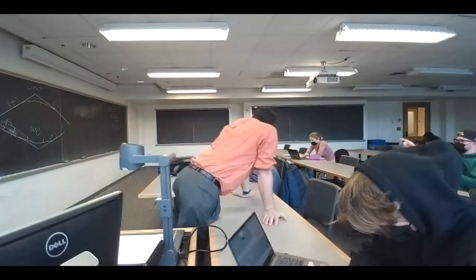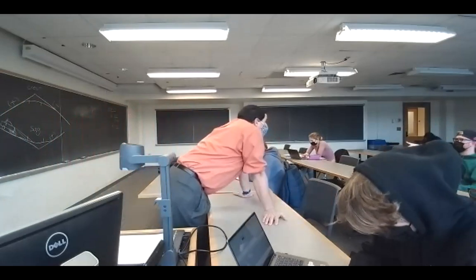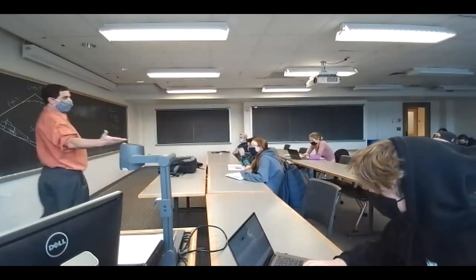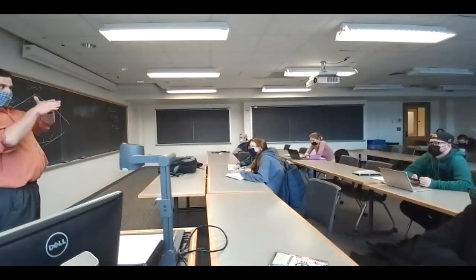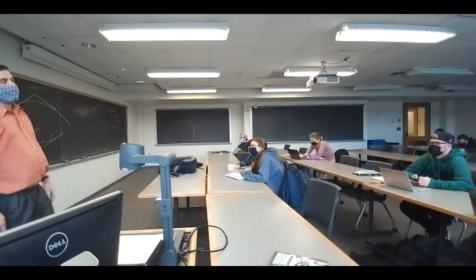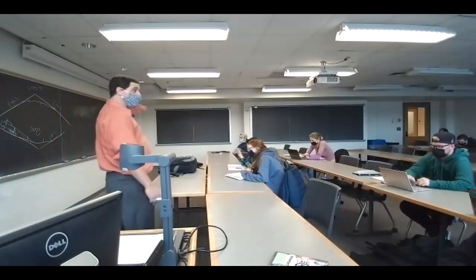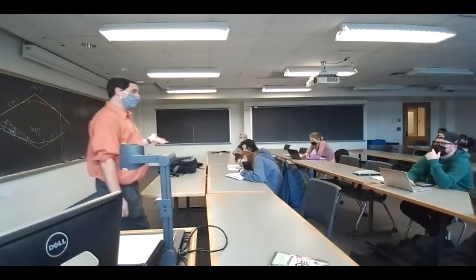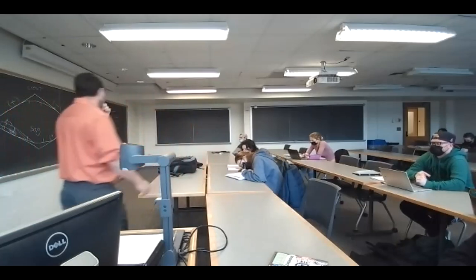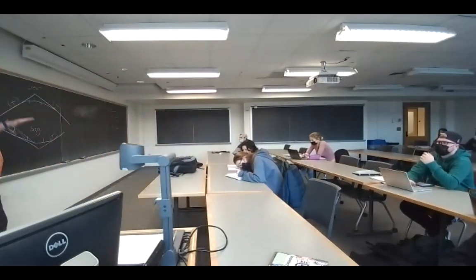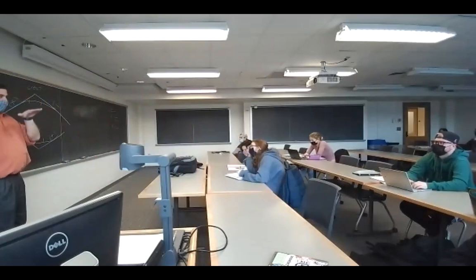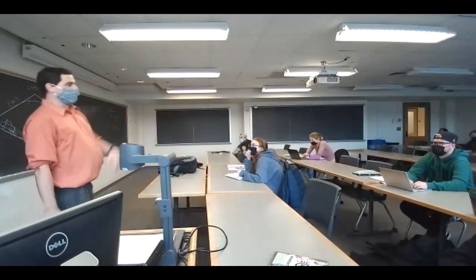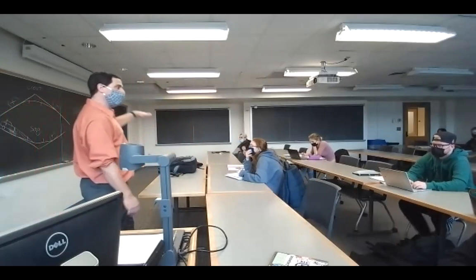Okay. So that less than 1%, I'd assume that'd be over a distance, because then you could vary it like 1% a foot later, another percent. Right. I mean, typically in your roadway design, you're running one tangent for several hundred feet. So when we do construction layout, we lay out the roadway every 50 feet, except along a vertical curve, then we're laying it out every 25 feet. So in all practicality, is the blade of a bulldozer grading a curve, or is he doing what you're saying, going every 25 feet? Yeah, that's more what he's constructing than an actual sweep curve.